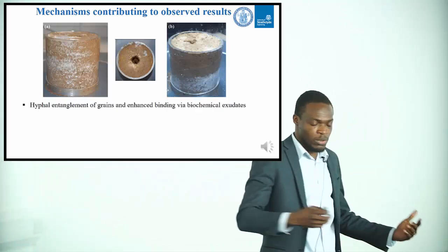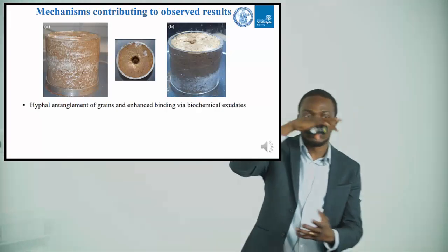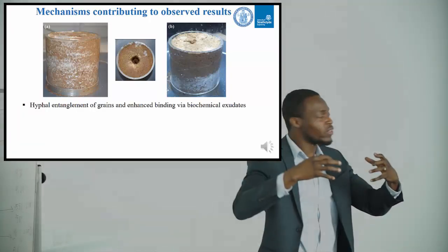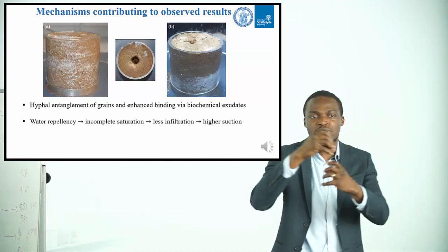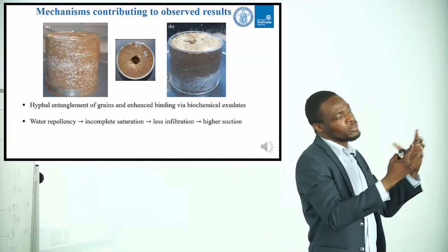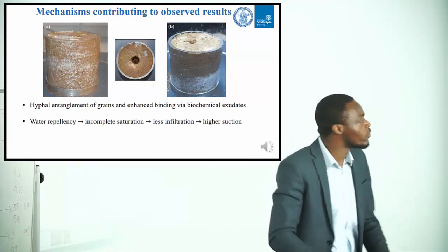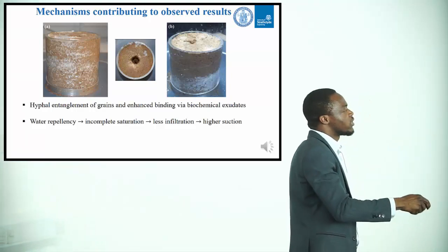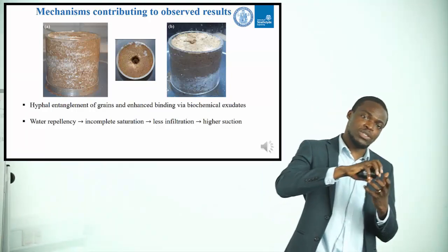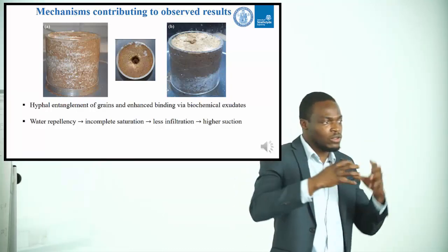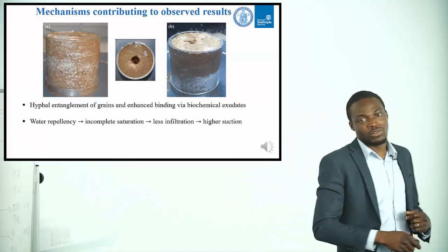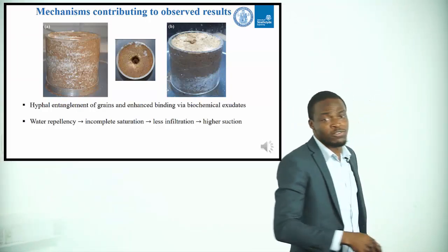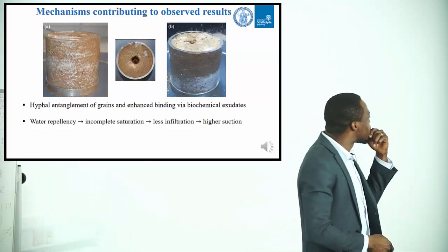This, we think, is probably due to less hyphal growth on the surface for 1 week, because the mechanism of hyphal growth and enmeshment of particles need time. And 1 week is probably not enough to grow through the profile of the specimen. And also, in the 1 week treated specimen, we saw that the soil was being detached in forms of aggregates, compared to in forms of particles, which you would see even in untreated specimen. Probably this is why the surface treated specimen even behave poorer than the untreated specimen.